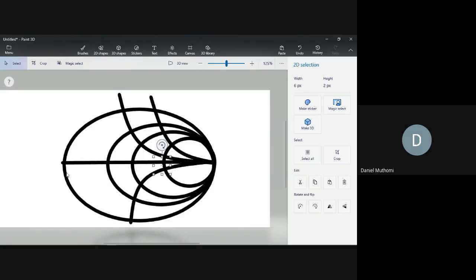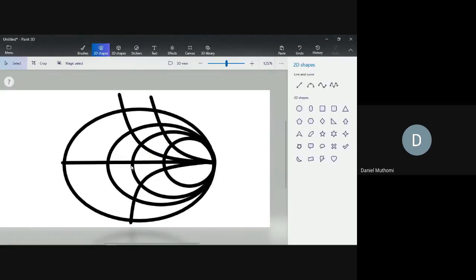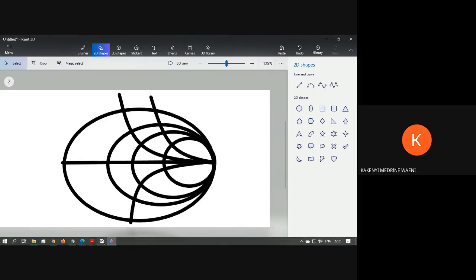We're taking the circle where r equals 1, or rather g equals 1, so we can't shift it. The only time you can rotate it is in double stub matching. For single stub, you only use the one that is there.